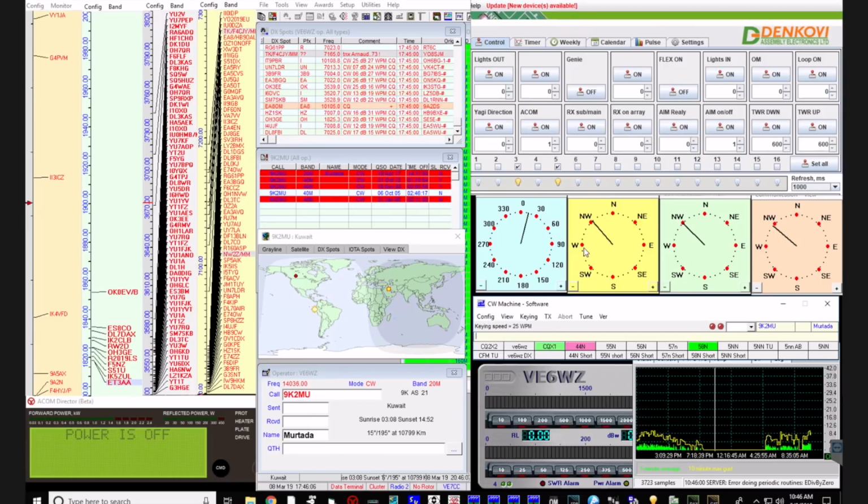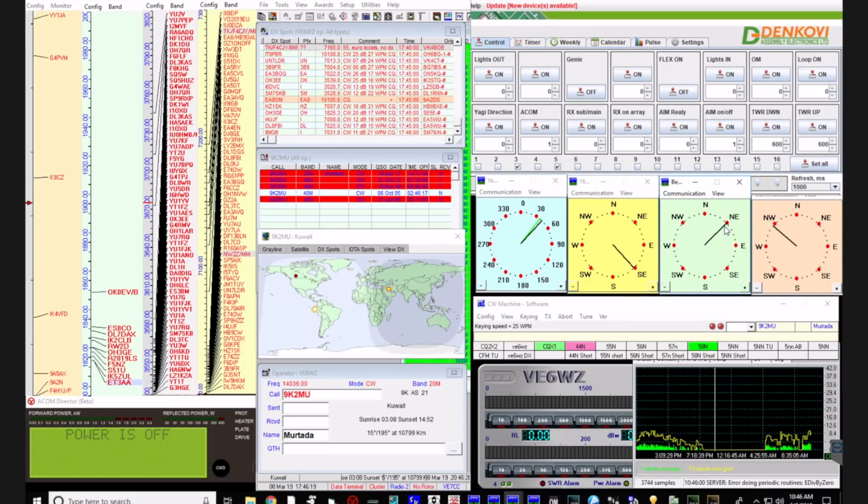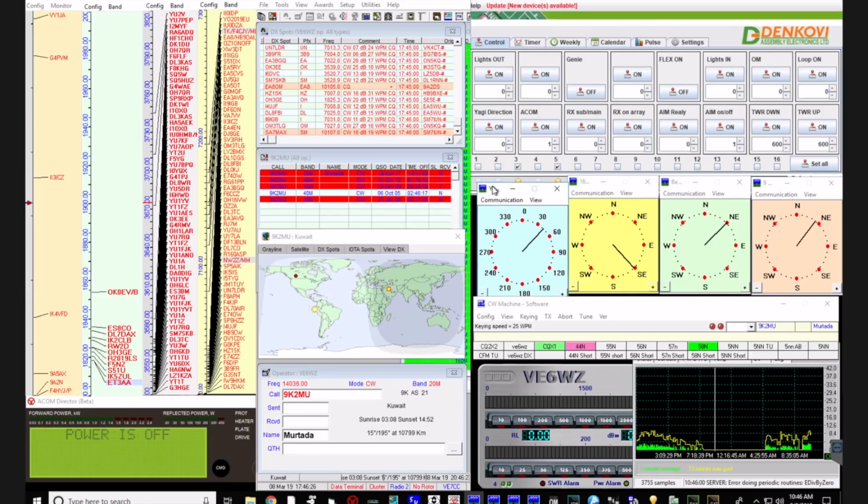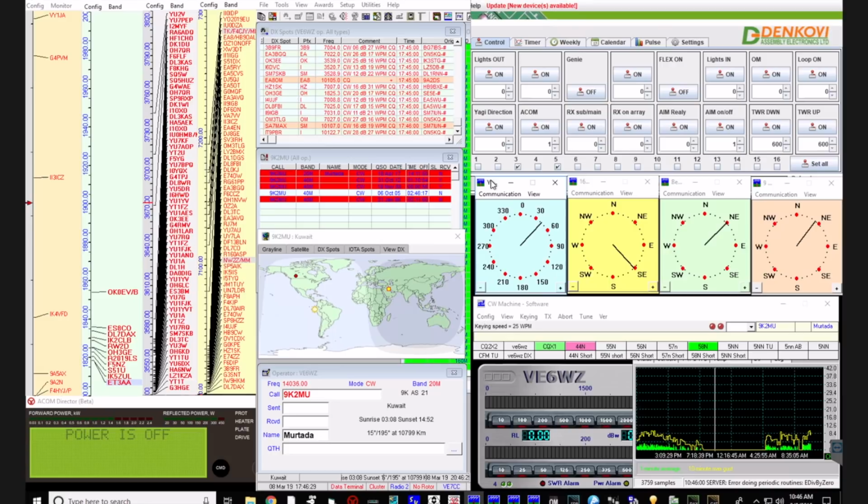These compass dials I've discussed in another video. This controls my Yagi, so I'm turning my 80-40 meter Yagi, the OptiBeam, by pressing that. This is controlling my 160 meter transmit array, and this is controlling my beverages and my 9-circle array. So that's how I control those, and these are individual windows which control the relay boards.